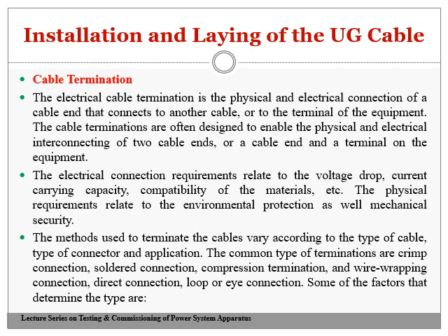To the terminal of equipment. The cable terminations are often designed to enable the physical and electrical interconnection of two cable ends, or cable ends to a terminal on the equipment. Jointing is totally different from termination. Termination is stripping off the end and connecting towards the one end.